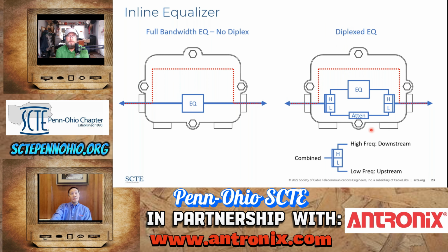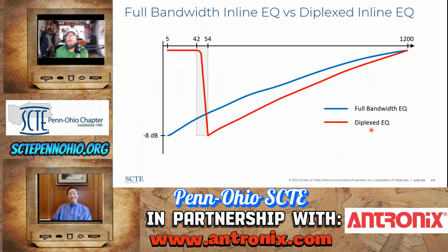Now, these did serve a good purpose back in the day. I promised myself I wouldn't say that, but I've been around for a while. And it's just an illustration of different design philosophies that different companies have had over the years, right? Certain companies wanted to have the largest footprint in their tap design as they could for efficiency from a power perspective. So that meant a lot of taps in cascade. And towards the end of lines through these long distribution networks, you needed to have equalization because of the amount of cable in front of it.